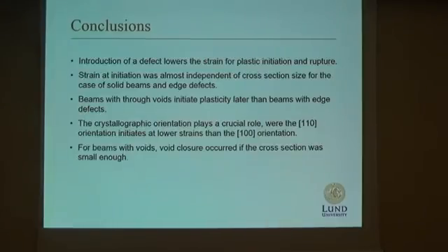We also saw large variations due to the crystallographic orientation, both in failure strains, strain at plastic initiation, and also the deformation pattern. And if we have beams with voids, we in some cases can have void closure, but that was only seen for the smallest beams and smallest voids.